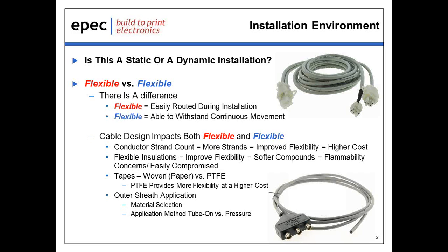Some of the issues that we can change from a cable: we can change the conductor, and we do that by increasing the strand count. Now, some of the issues with increasing the strand count, it will improve flexibility, but in most cases, it will result in a higher cost conductor.